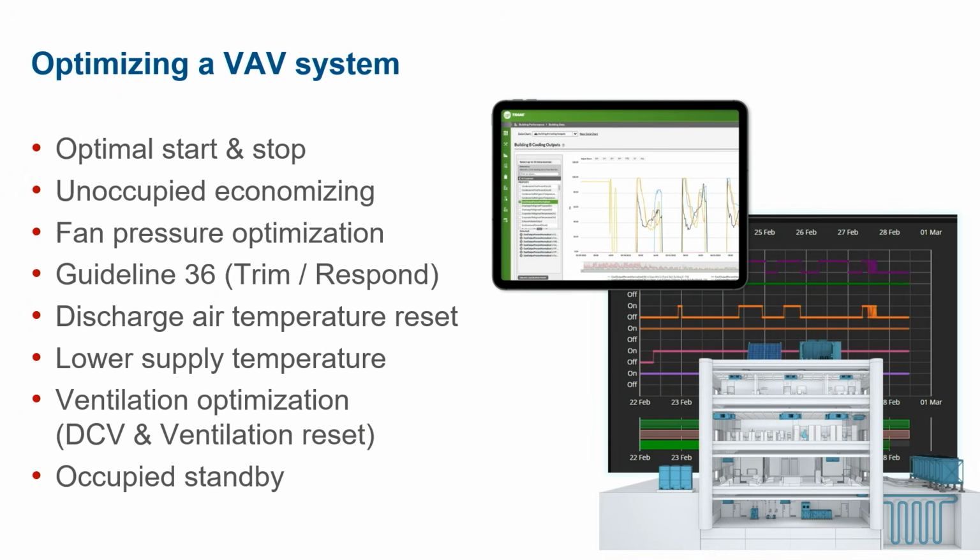Next, the team is going to discuss how to optimize a new or existing VAV system to reduce energy usage, emissions, and operating costs. And that usually starts with controls. To fully leverage the advantages that we will discuss in this section, it is advisable to implement a building automation system, or BAS. Modern BAS systems are both robust and interoperable. These systems can come with prepackaged control algorithms, streamlining their deployment and reducing costs. Additionally, a building automation system ensures continuous optimization of the building, enhancing comfort and energy efficiency.